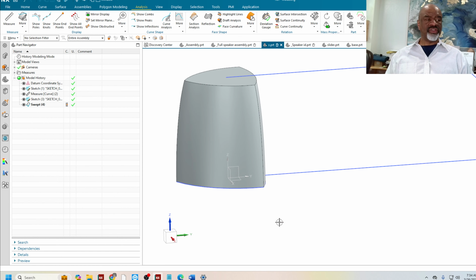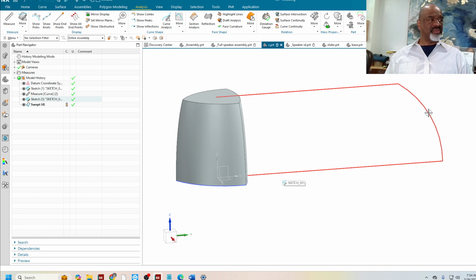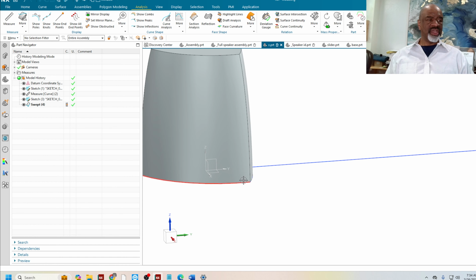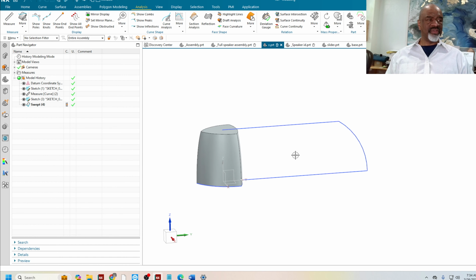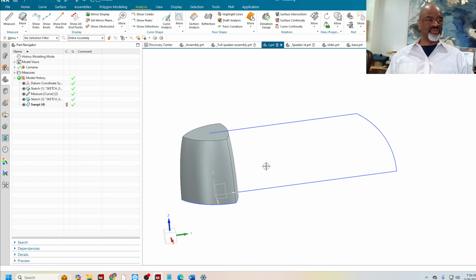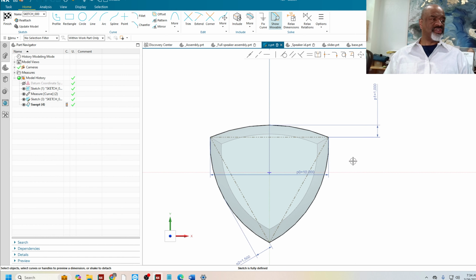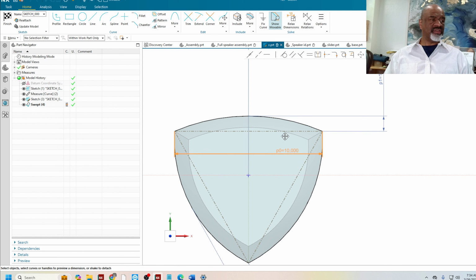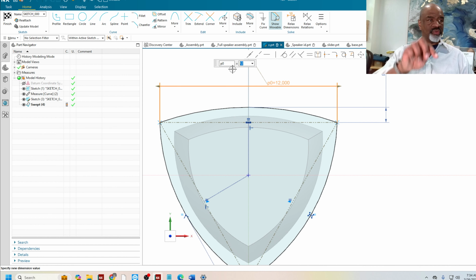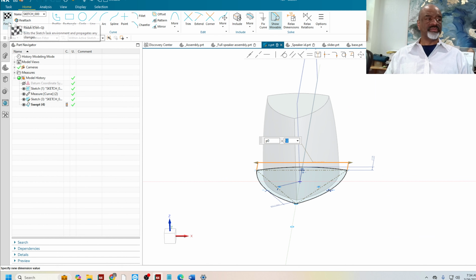So if I should change the section, I would hope that this piece of geometry changes also, and then I still get the ability to taper this thing any way I want, or as much as I want, as I'm driving it. So let's do a little test. Let's go back to the original sketch. The original sketch had a dimension, here it is, 10 inches. And if I change that to 12 inches, let's say, 12, then the whole section, of course, updates.